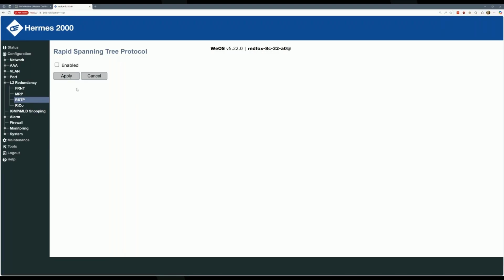All right, quick question answer here. The question is, in 61850 GOOSE applications, how important are VLAN IDs? They'll be used for sure. You have to make sure the traffic does exactly what you want.